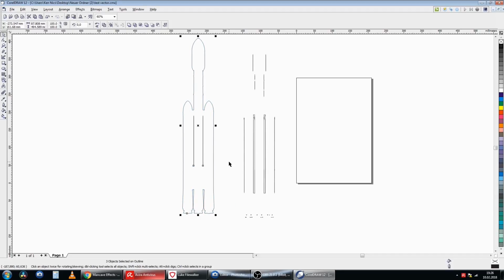And then we try to drag it over again, and you see there are multiple lines as well. So this is basically the classic problem with autotrace. You have so many lines that are doubled that it risks your laser cutter will burn your working piece later on. That's why I want to trace this manually, but I wanted to show you that when you have a simpler picture or a simple object, you can auto trace, and then you can simply cut it right away. But in this case the graphic is too complex to easily just make it cut automatically.